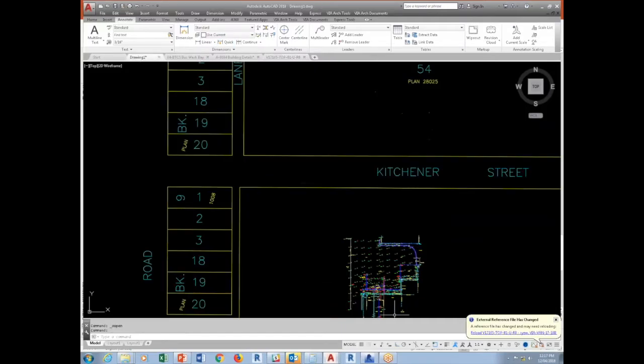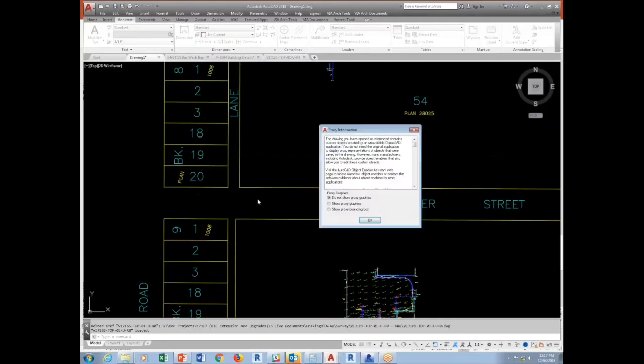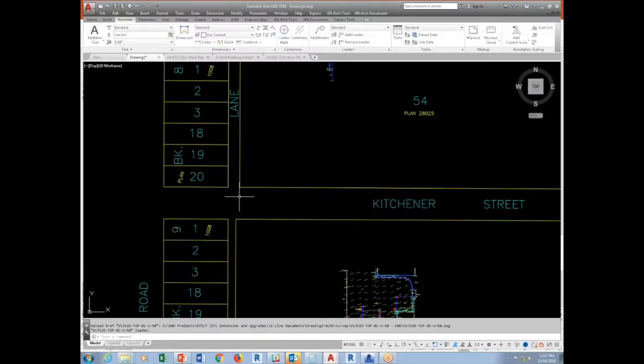Okay, when you save that, I'm going to go back here, and when you reload it, you notice that the insertion point changes. You can modify that. This is one per drawing, but you have to make sure that when you do this, you tell engineers that for our drawings, this is the insertion point that we're using. Sometimes they understand, sometimes they don't, depending on how you do it. But this is how I get all my drawings closer to 0, 0.